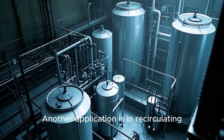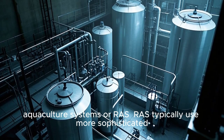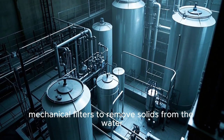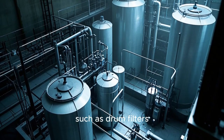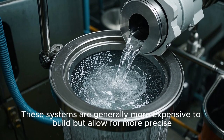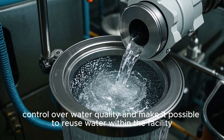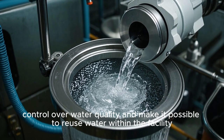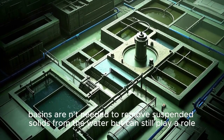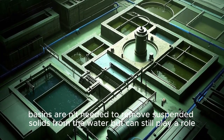Another application is in recirculating aquaculture systems, or RAS. RAS typically use more sophisticated mechanical filters to remove solids from the water, such as drum filters. These systems are generally more expensive to build, but allow for more precise control over water quality and make it possible to reuse water within the facility. In these systems, sedimentation ponds and settling basins aren't needed to remove suspended solids from the water, but can still play a role.